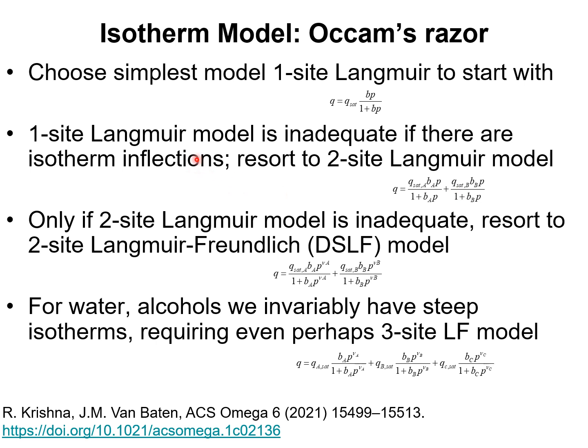For example, if I have adsorption of say normal butane or isobutane in MFI zeolite, where the isoalkane locates preferentially at the intersections, the unary isotherms show strong inflections that can only be captured by a two-site Langmuir model.